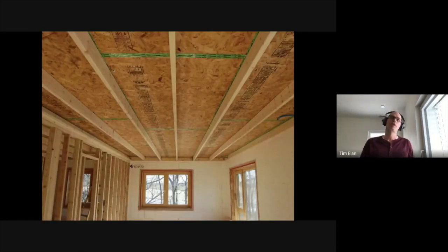This is maybe worth talking to for a second. A lot of times what we'll do at the lid is create a dedicated service cavity. So what you're looking at is an OSB sheathing fully taped up, used as a vapor retarder and air barrier towards an attic. And then below that, a service cavity. I believe these were 2x6s that are used to run services. It's great to separate that out. It's not required, but it is a great way to do it because now we don't have any weaving in and out of the airtight barrier of any of the services.